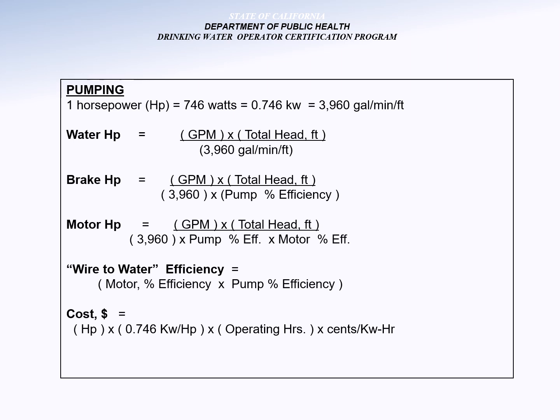So a lot of this is stuff that we've already just been talking about, so I'm not going to get too deep into this, but you do have your individual formulas for calculating out your water horsepower, brake horsepower, motor horsepower. But when you're actually going through the entire thing, you're starting with your motor horsepower, then your brake, then your water. And then you can always calculate out how much money it is going to cost us to operate this pump.